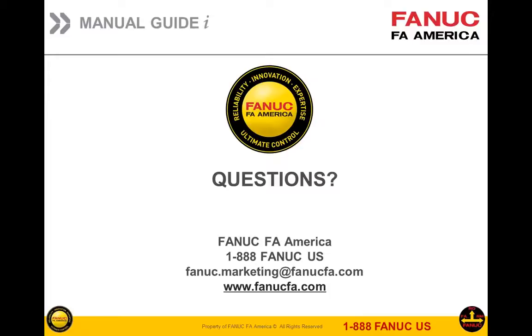All right. Another basic question here from the audience. Is the D offset 1/2 the tool? Now, assuming that's the diameter offset, 1/2 the tool diameter. Yeah, it's the radius of the tool. Yeah, it's radius, 1/2. Okay. I know I kept saying diameter, but that's just the way I reference the D word in my mind. I always say diameter, but actually I mean the radius on a mill.